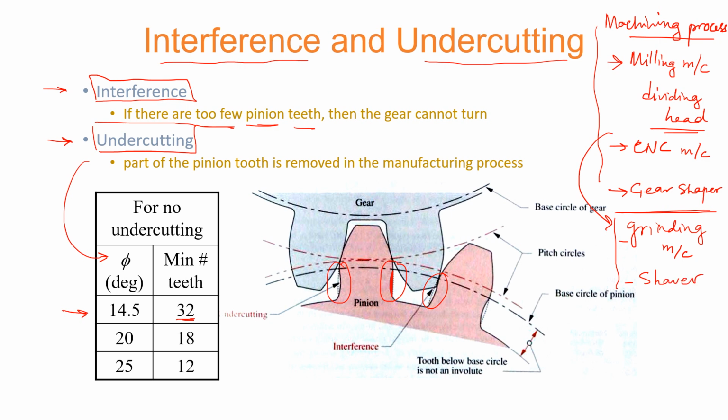You have a very sharp shaver tool mounted on this machine, and it removes the fine material on the flanks of these gear profiles. So these are a few alternate options, and once you perform these super finishing operations, you remove or reduce the noise, and you reduce the vibrations as well.